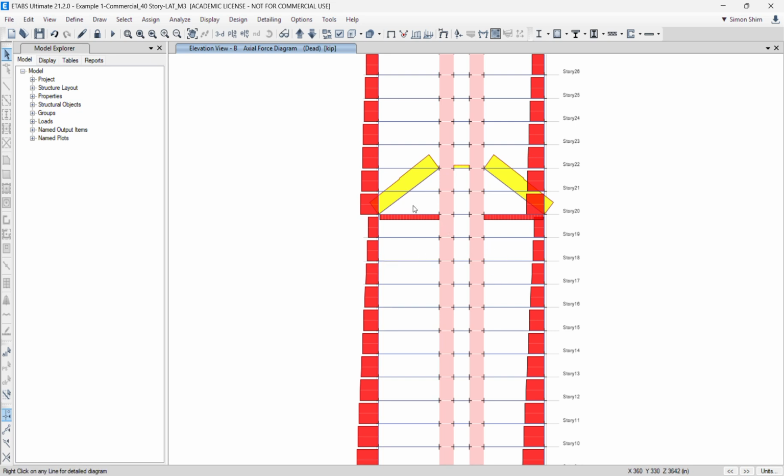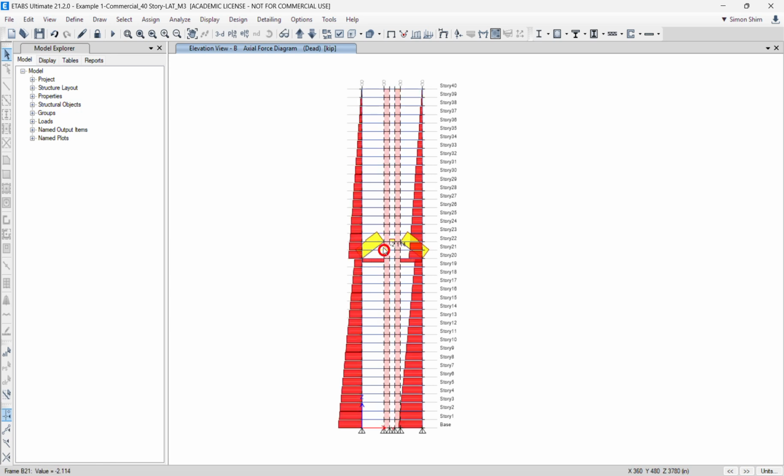So in these cases, we should run the construction sequence analysis so that during construction, we skip the full connection of this bracing. When we erect, we temporarily connect or don't make any connections, so that this bracing is not fully installed when the building is topped out.